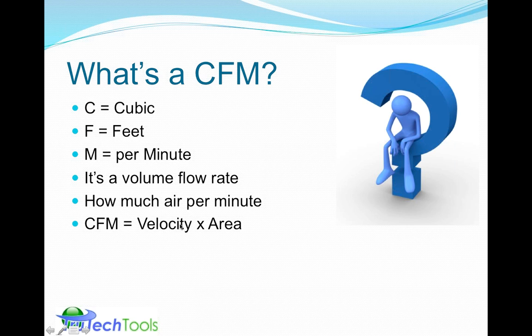So when we have these two factors we're combining together, most of the time what we're actually measuring is air velocity. We're measuring air velocity with the measuring device, and we're multiplying it by the area, the intercepted area, the cross-sectional area, the area this velocity is moving through. So in many cases you have to take an average velocity, because it could vary across the area, in order to get the total CFM, and the open area calculation is critical to getting a correct CFM.